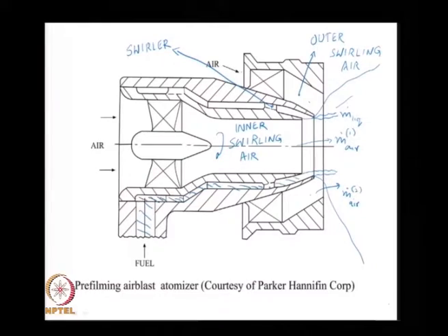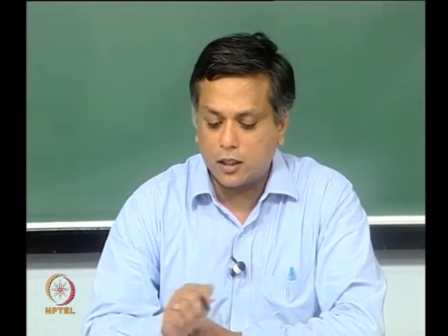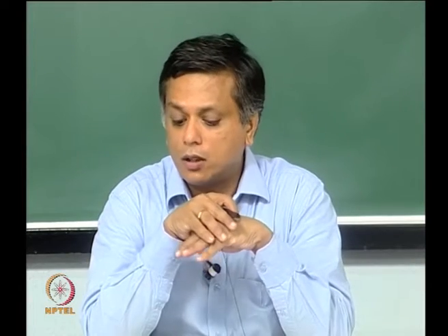The air coming in is essentially the compressor stage exit. So, it is at a fairly low pressure, maybe an increase in the pressure ratio of 2 to 3 at the compressor stage. So, we are looking at fairly low pressure air, and the liquid is also operated by a pump that is typically on the same shaft. So, that is also a low pressure liquid, but the flow rate of the air is very high, and that is what gives us good atomization.